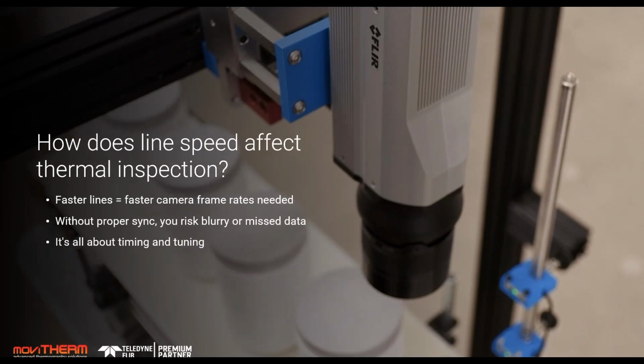With the uncooled cameras, they have something called time constants, and the time constant with uncooled microbolometers is typically in, let's say, the 6 to 8, maybe 10 millisecond range. So as the bottle cap goes by the uncooled camera, if it's running anything really higher than 70 linear feet a minute on the conveyor, we're going to start to encounter blurriness. That's the key factor here. If it's over 70 feet a minute, even if you have a standard cap, we're really going to be forced to go to a cooled camera, the A6301.